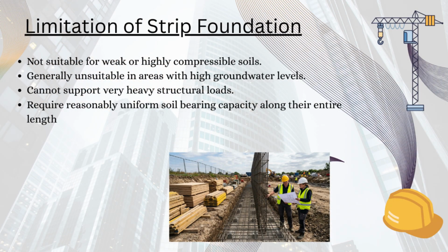Like every foundation type, strip foundations also have some limitations. They are not suitable for weak or highly compressible soils, where excessive settlement may occur. They are generally unsuitable in areas with high groundwater levels, unless proper dewatering and waterproofing measures are implemented during construction. They cannot support very heavy structural loads as efficiently as raft foundations or pile foundations. Finally, strip foundations require reasonably uniform soil-bearing capacity along their entire length. If one section of the soil is significantly weaker than another, differential settlement may occur, which can cause cracks in walls, uneven floors, and even structural instability.